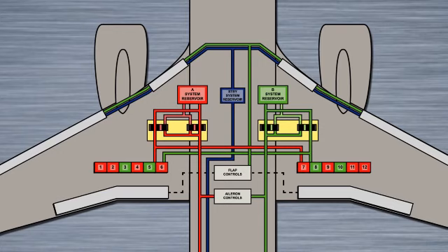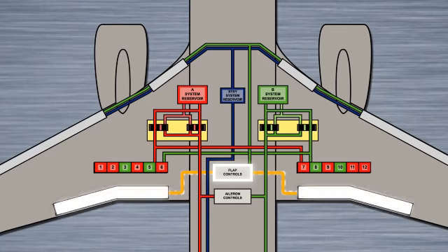When the flap lever is moved, commands are given to a flap control unit that uses hydraulic system B pressure to move the trailing edge flaps through a power drive unit, PDU. The PDU converts hydraulic pressure into mechanical force to operate the trailing edge flaps. The PDU also has a valve by which flap extension may be bypassed. Leading edge flaps and slats may be controlled by one of two ways: hydraulically or electrically.